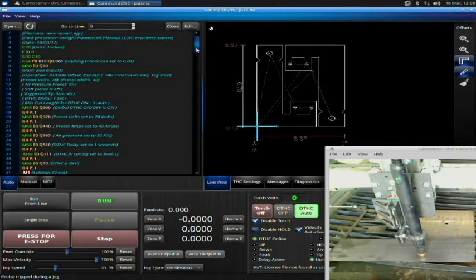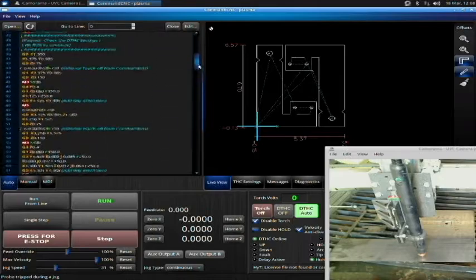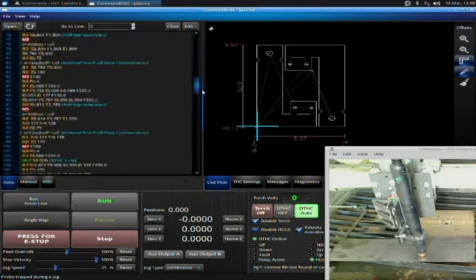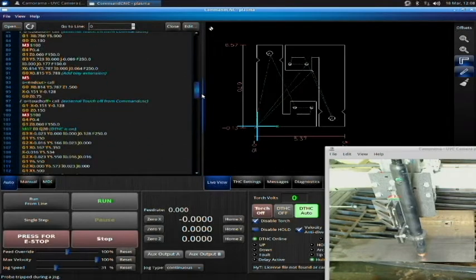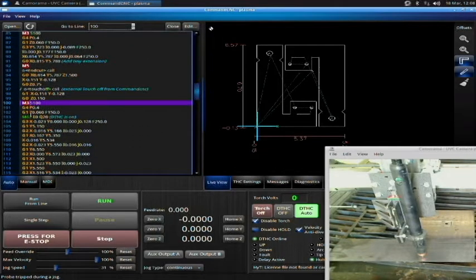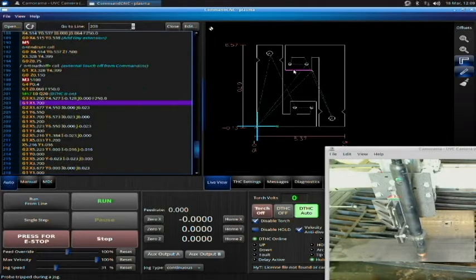As we talked about before, this G-code is a series of instructions. And so by moving to different points in the G-code, I can move to different points in the cut. Say for instance I click on that M3, that is indicating a move over here. I can click on this display and it will take me to that particular line of code that I'm clicking on. So that's very handy.